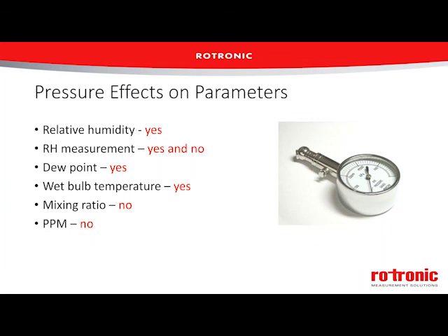A change in pressure absolutely will change our relative humidity, but we don't always need to be as worried about changes in pressure as we are changes in temperature. The changes in temperature are far more likely to affect our actual measurements, whereas pressure not always as much.